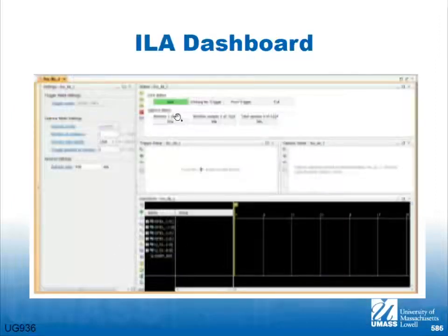And then this is a little blurry, but then I go through the same dashboard that I use to load the software and load the hardware in the FPGA, and it brings up the Logic Analyzer dashboard, right? And it has the start, to wait for a trigger. It has single trigger. It has repetitive trigger, all the same things that a normal Logic Analyzer would have, and the scope had in my first example.